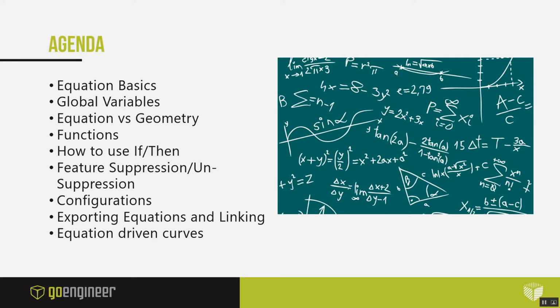You can use equations to turn things on and off, how to configure equations, and how to use equations and configurations. You can export equations if you got them created, and you can link them to a file. I'll show how to do that. And then I played around a little bit with equation-driven curves at the end, just to kind of show some of that if you haven't seen that before.